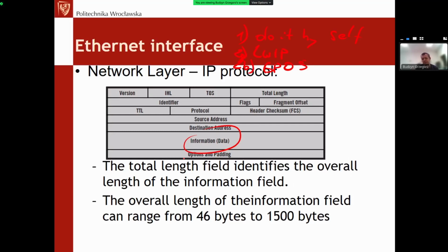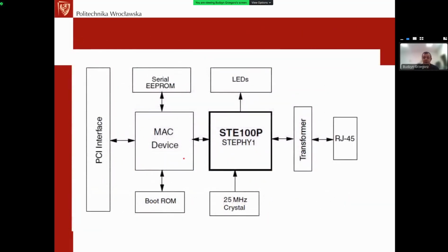If you want to use cases number 2 and 3 of the Ethernet, so the local connections or Profinet, for Profinet and for local, you will need some additional layers implemented. Not link layer, but network layer, because the IP protocol is network layer. You would need some network and application layer. You would need to add them, but of course they will be much simpler than the pretty heavy TCP/IP stack that's not required for the Internet.